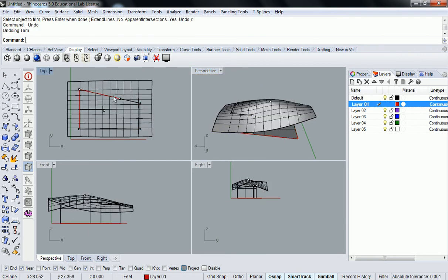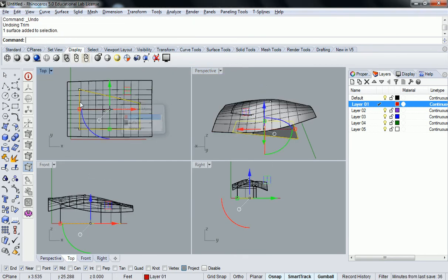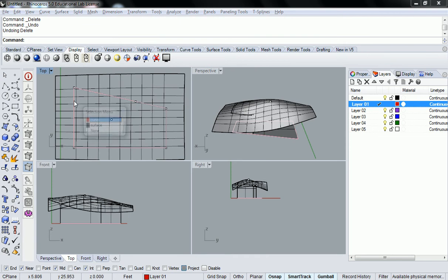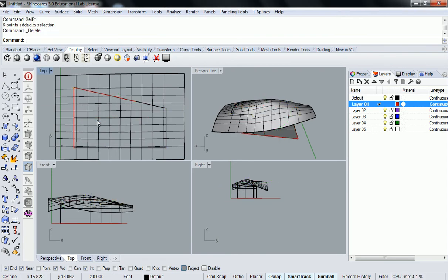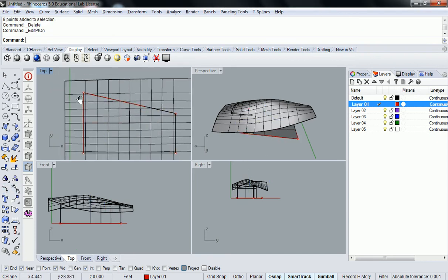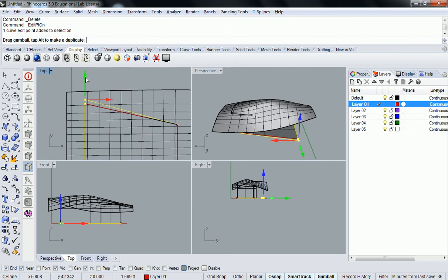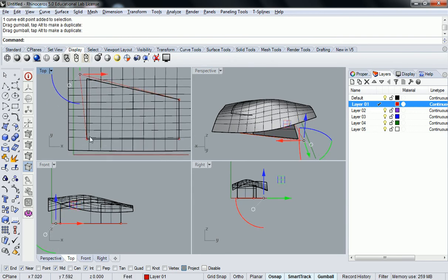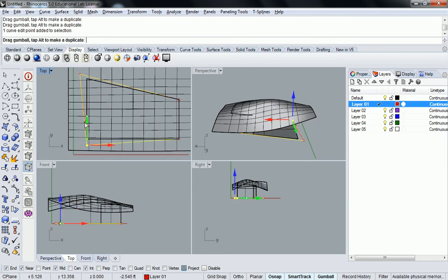The other thing you can do is actually, if you're going to go through the process of designing it, you can draw your original profile. Let me get rid of those points. I don't want them. Grab the original profile, turn your edit points on, and start playing with those. So you can yank them off and make it kind of a skewed profile if you want.